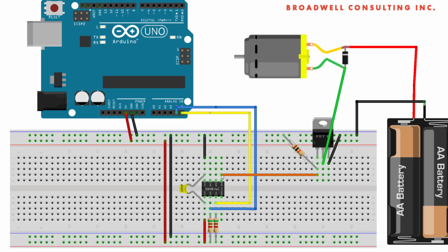Then when the Arduino was actually finished with this, we would reconfigure this pin back to a low output to shut the motor off. But in the event that the I2C traffic stopped or the Arduino locked up, you've already set a timer on the Serial Wombat, which says, if I don't talk to you for 2 seconds, shut off the motor automatically.